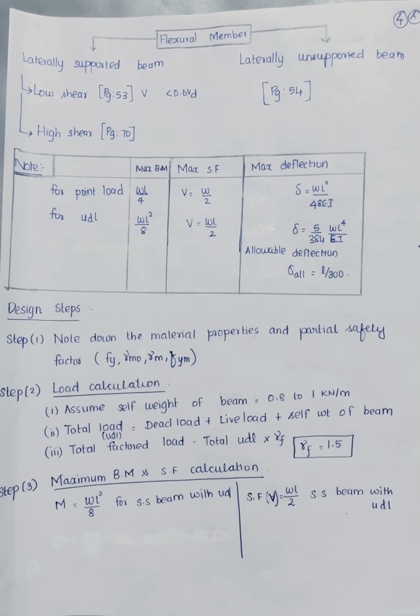Flexural member, that is beam. In this lecture, we'll understand the design steps involved in solving laterally supported beam and laterally unsupported beam. In laterally supported beam, there are two conditions, low shear and high shear condition.